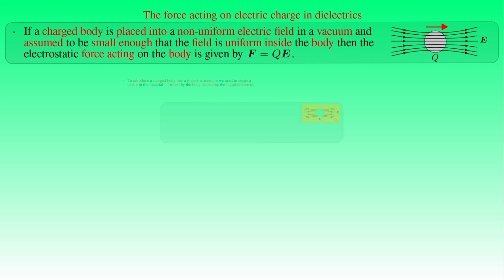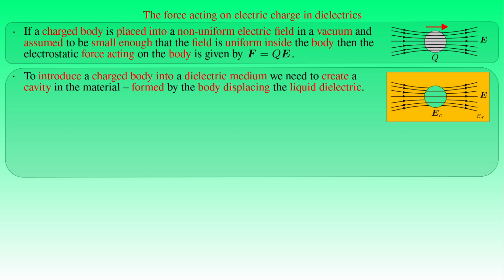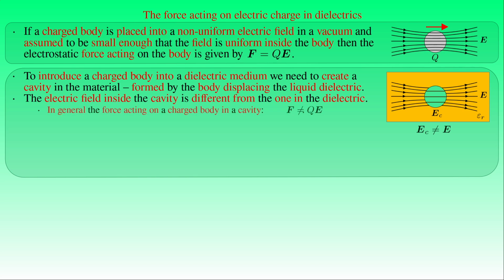In order to introduce a body with the charge Q into an electric field E in a dielectric medium, we need to make a cavity in the material. In a liquid dielectric, the body forms a cavity around itself in such a way that it displaces the liquid from the volume it is to occupy. The field strength EC inside the cavity will be different from the field strength in the dielectric medium. Hence, the force acting on the charged body in the cavity cannot be equal to the product of the charge Q and the field strength E in the dielectric.